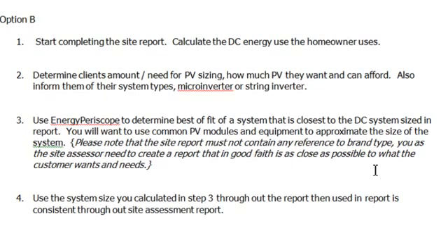Very common modules that you would see are Kyocera. You've got some older Kyocera, then you've got Evergreen Solar out there. You've got a lot of others, like Grape Solar. But here's what I recommend. Kyocera, maybe the BP. Go to a company like Sun Electronics. Go to their website, see what models are out there, and then get an idea of what the costs are for those. And choose a model right now about 230 watts. That seems to be a common module that's out in industry.